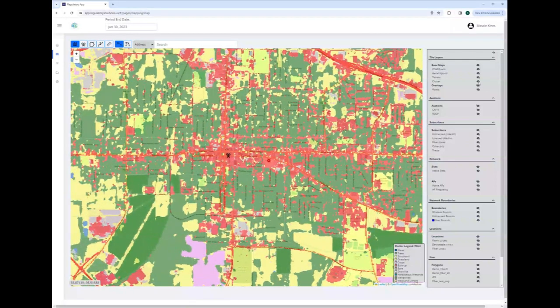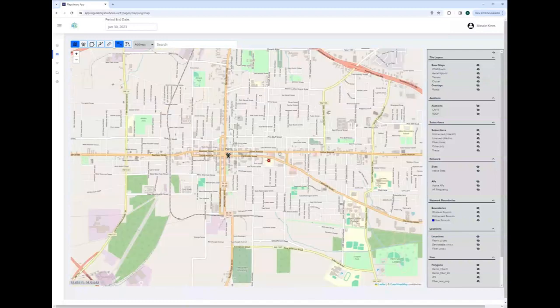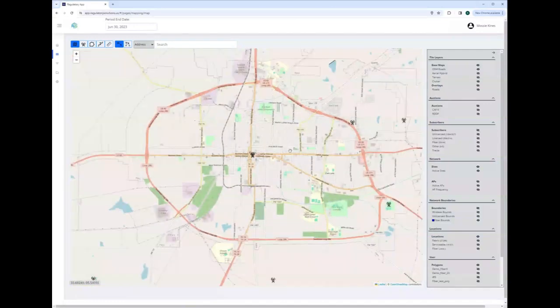So we actually think this is a little bit better than using LiDAR data. Most of the LiDAR data that's in use by other tools in the space is using just the first echo return, which means that it's going to show everything as terrain. So even your trees, your buildings, everything kind of shows up as just one big blob of solid object.